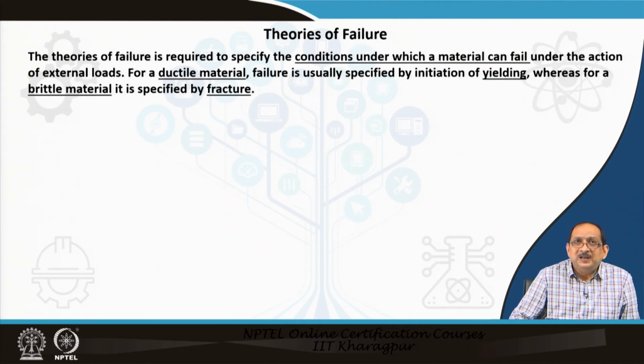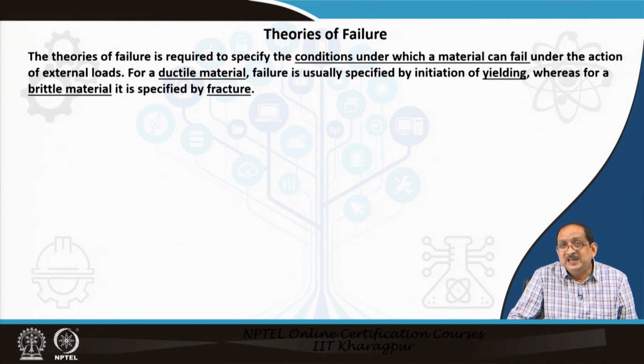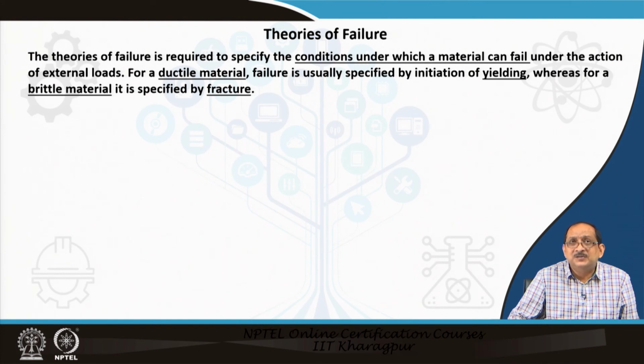The theories of failure are required to specify the conditions under which a material can fail under the action of a set of external loading conditions. For a ductile material, failure is usually specified by the initiation of yielding, whereas for a brittle material, it is specified by fracture.